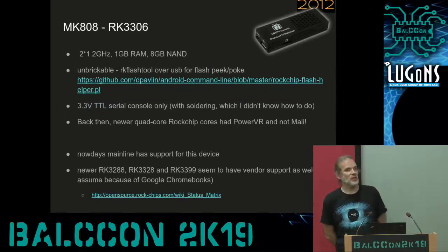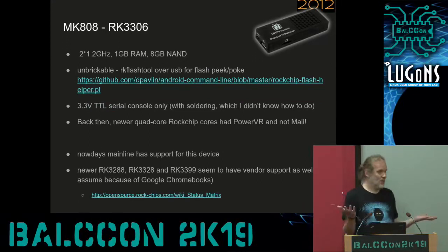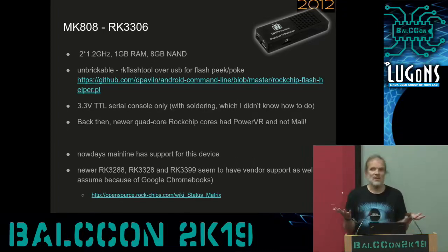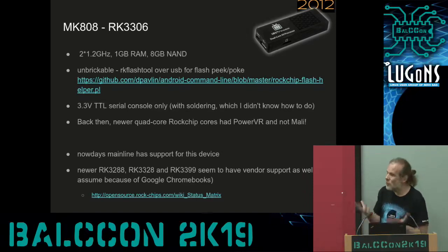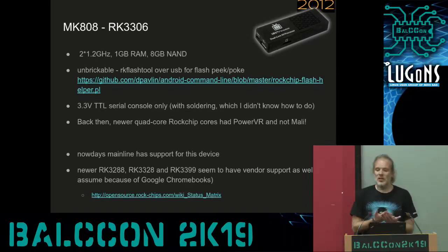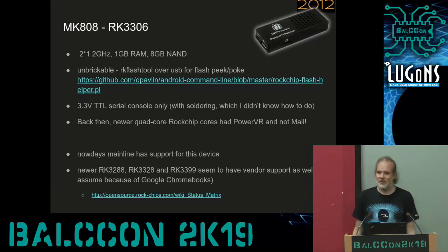You might ask the question, why would Rockchip do something like this? Because when they produce the dongles in the Chinese factory, they solder all the components on the board, but the board itself is empty. The NAND chip on the board doesn't have the operating system, so they do need some kind of mechanism to do the initial load. And we can use the same mechanism to actually take over control of the device.